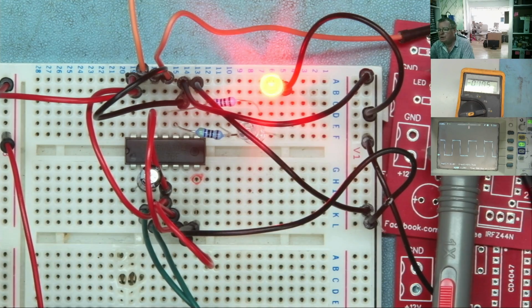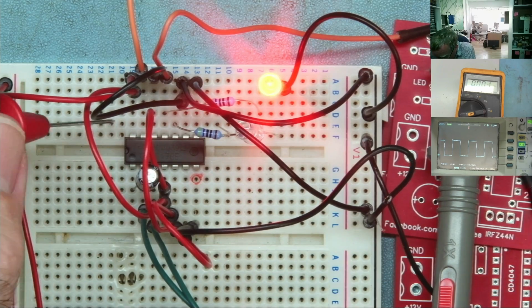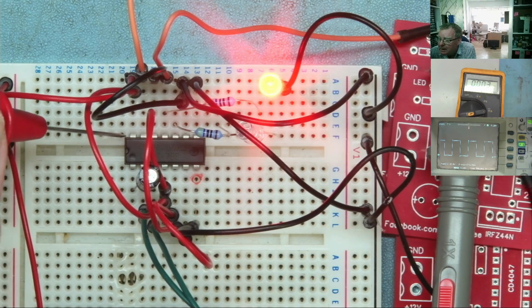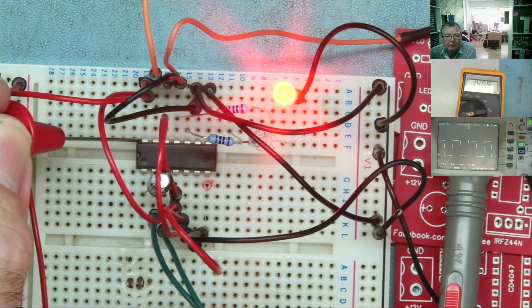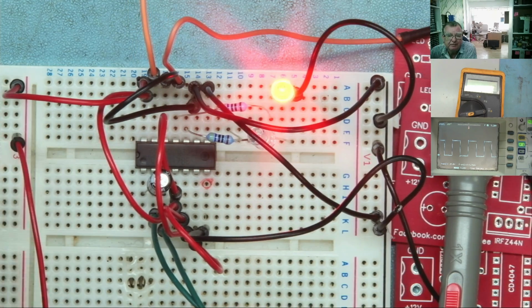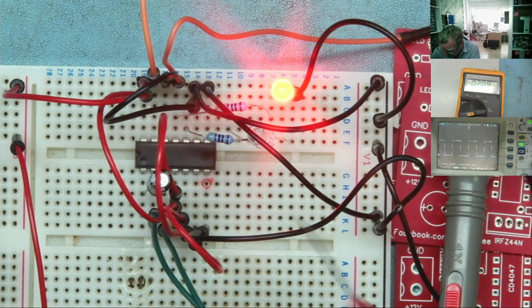Let's check this then. So VDD, this actually means voltage to the drains. You'll sometimes see VCC, voltage to the collectors. This is your positive supply. So don't let that ever confuse you. And we have pin 14, 15 volts, that's supply, and then 4, 5, and 6.